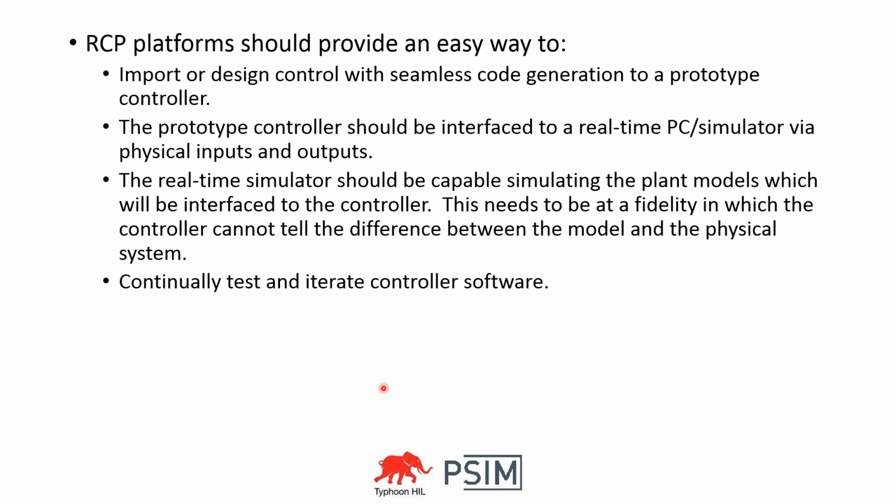The prototype controller should be of the same processor family and should be very similar to your end development board, which you'll be using. And it should be interfaced to a real-time PC or simulator via real physical inputs and outputs. You don't want to make any modifications to your controller when you're doing this testing, just so that you know that everything is going to be working perfectly once you move it to the real hardware.